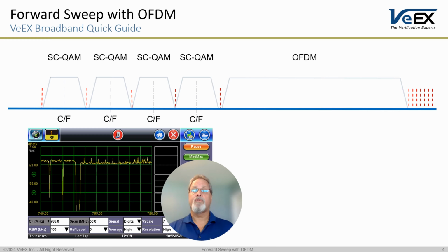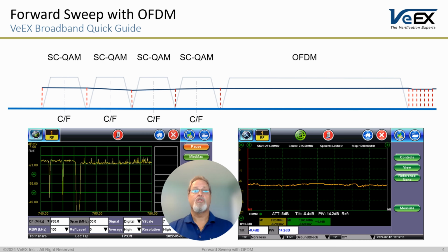So with traditional sweep in an old method, or our past method, when we would go and make our measurements for the sweep tones, we would then trace our measurements and end up with a straight line pretty much going straight through the OFDM, which means no measurements were done in that bandwidth. So as you can see in the sweep trace, it comes out looking like this when you look at a sweep trace done with bypassing or ignoring the bandwidth of the OFDM.